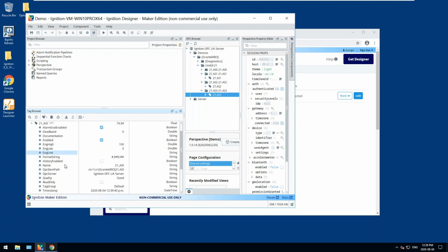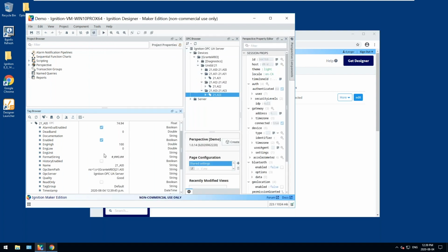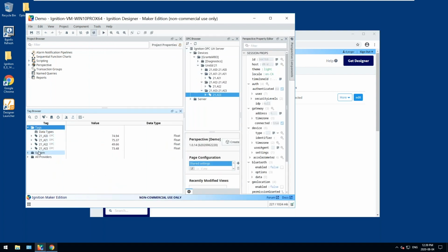And if you notice in here, we have no unit. The engineering units is blank. It's because nothing was published, because this isn't a subscribe-publish. It's polled. So I'm just reaching out to it and saying, please give me your values. So there's a lot more configuration on this, whereas MQTT is publishing that information, and it's common across anyone who's using it. If you had multiple people trying to read this Modbus information, you'd obviously be reconfiguring the same information over and over again. So that covers setting those back up.